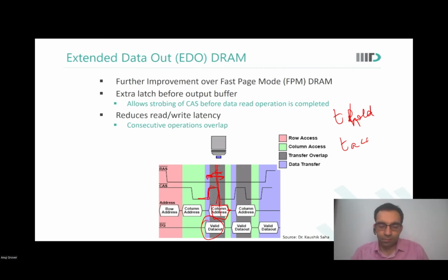Sir, I want to clarify, in the row address, when we give the row address, that row will be decoded and the sense amplifier will sense it, so that the complete data of one row will be at the sense amplifier terminal. Yes, that is latched either at the sense amplifier level or at the layer of this n cross m memory SRAM.